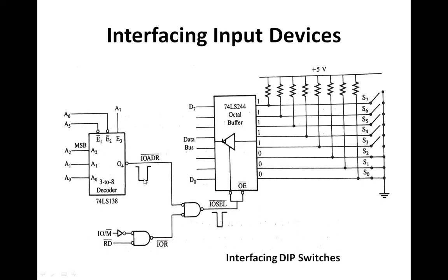So in that particular case, we will be providing the instruction IN 84. IN is the instruction opcode, and whenever this opcode is executed by the microprocessor, it will come to know that it is a 2-byte instruction. So the second byte will be fetched and executed, by which it will be able to know that 84 is the port address which it has to read.